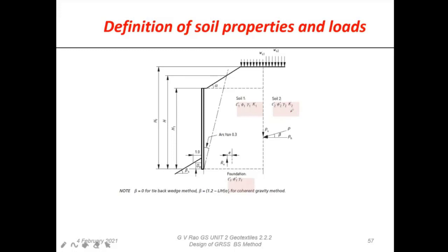Okay, and then soil 1, of course, is the soil which is selected by us for making the wall now, because it becomes the reinforced soil mass. We want it to be in general free draining. We want it to have good friction, because once the soil has good friction and good density, it is going to give you good resistance for sliding and the bond also. So this is a select soil, you can say, like I've shown you in the earlier patents, old patents now. So again, we are going to think of the values of C, phi, everything else in the same way.